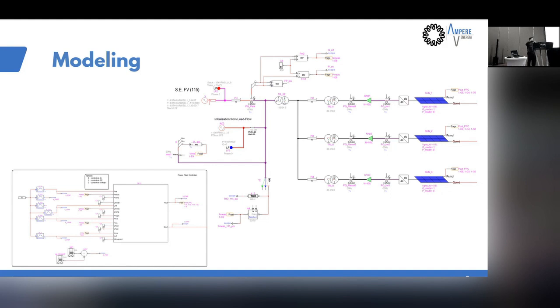So that's a huge challenge that we already faced, because sometimes we lose a lot of time just simulating, and we try to use a larger integration time step, but results change a lot. So we have to keep that time step.